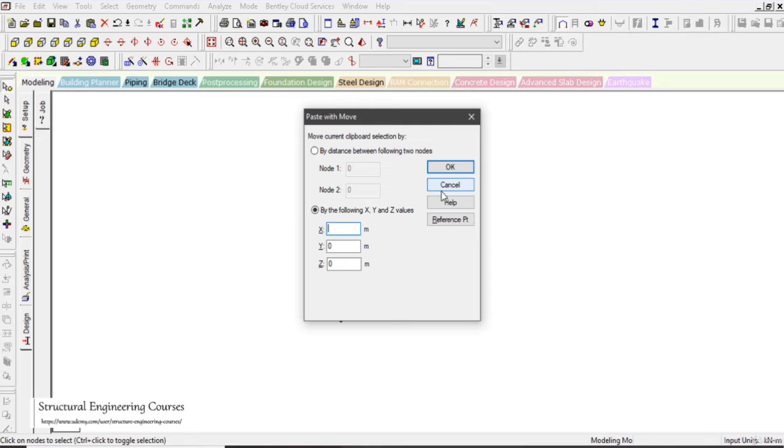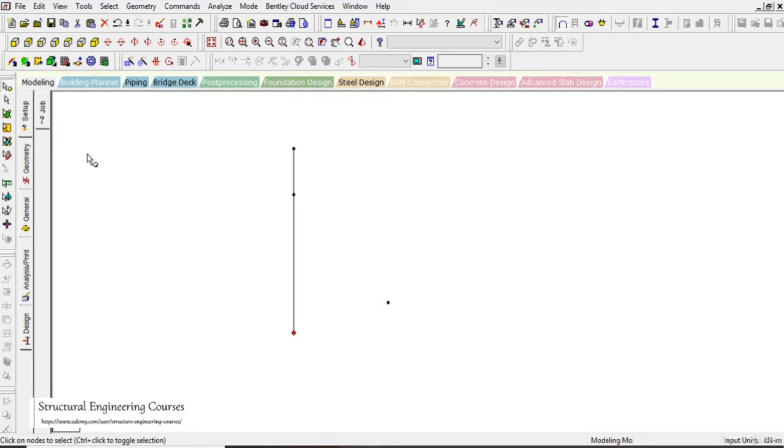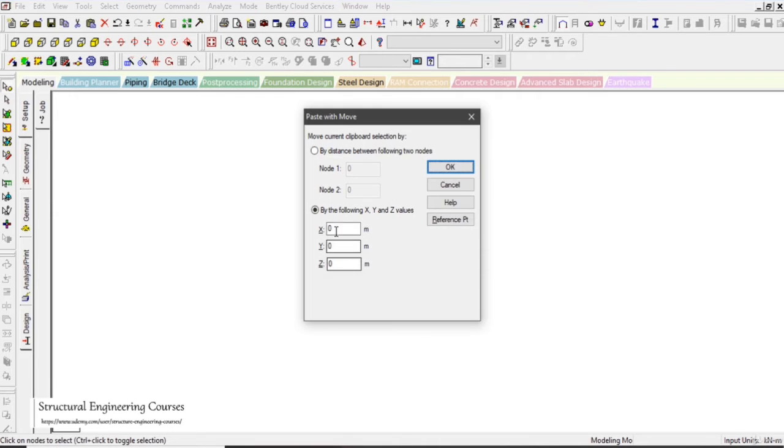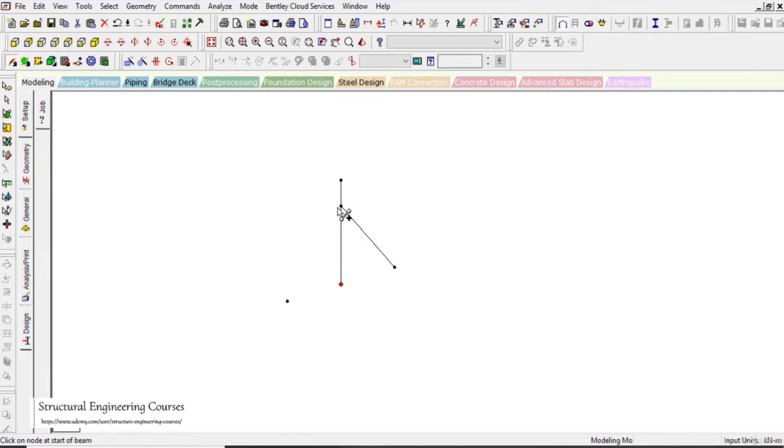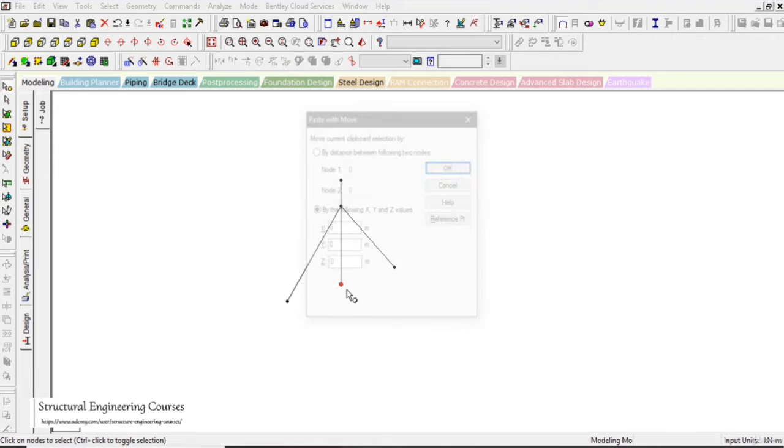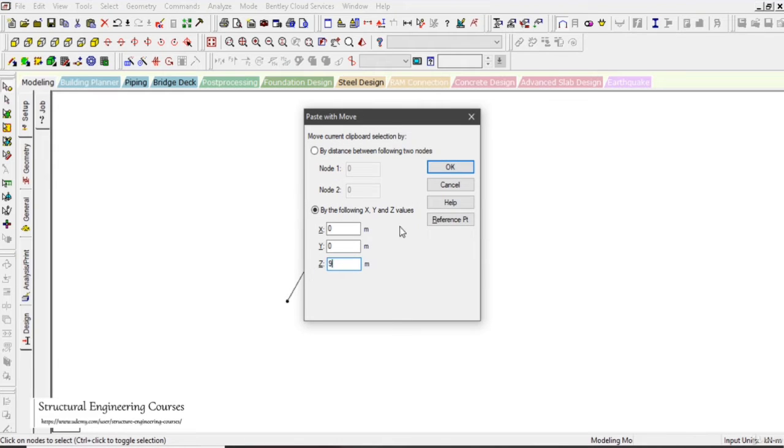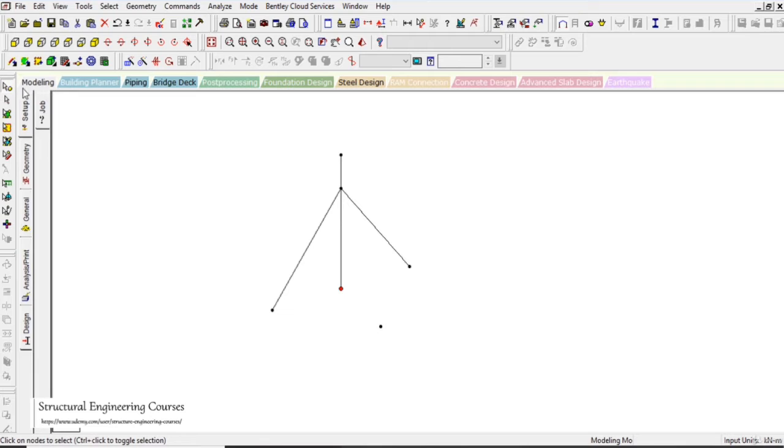X as 9 meters. So selecting X equal to 9 here, we can model a cable here. After that again we can copy paste this particular joint as X equal to -9, and then we can again model the wire here, and then after that we can go to this element as Z. So again we can select this Z as 9.